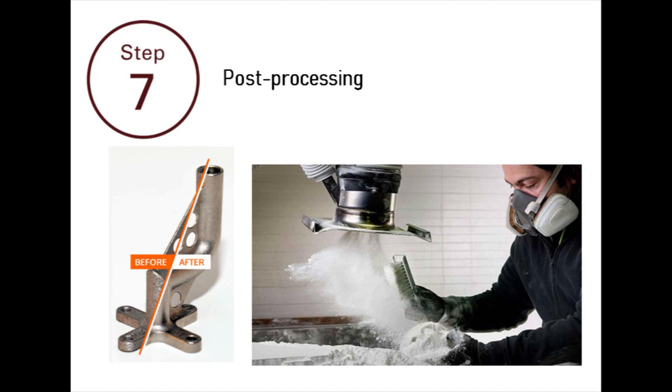Different additive manufacturing processes have different results in terms of accuracy and material properties. Some processes produce relatively fragile components that may require the use of infiltration or surface coatings to strengthen the final part. As already stated, this is primarily a manual task due to the complexity of AM parts. However, some of the tasks can benefit from the use of power tools and additional equipment like polishing tubs or drying and baking ovens.